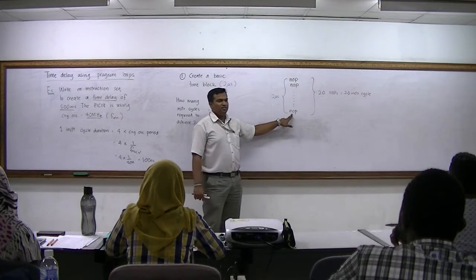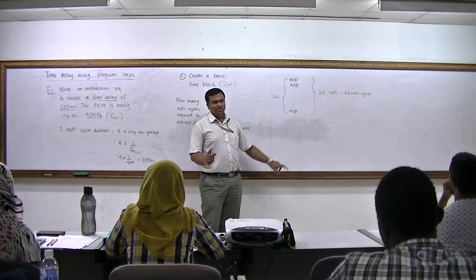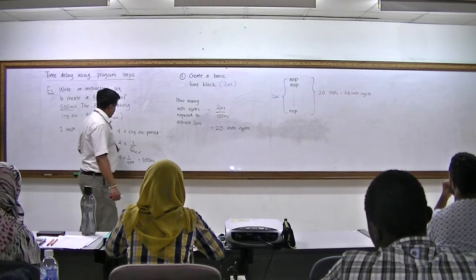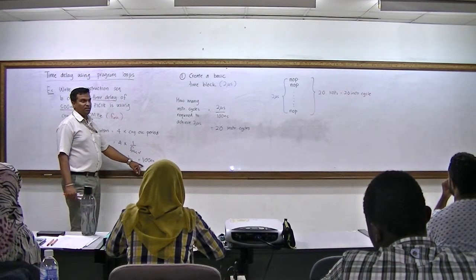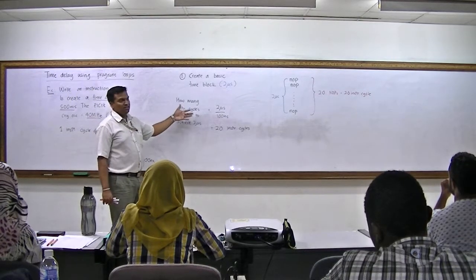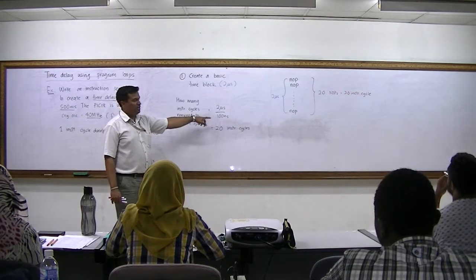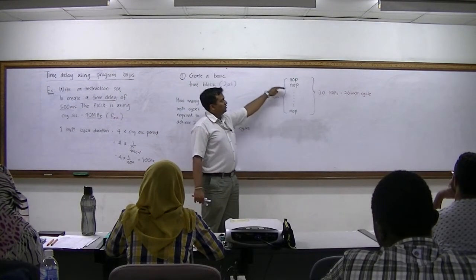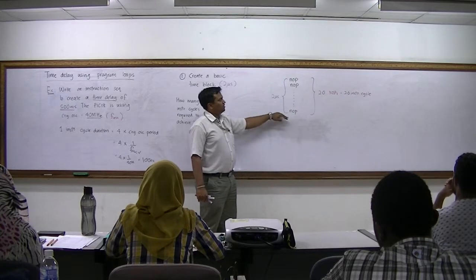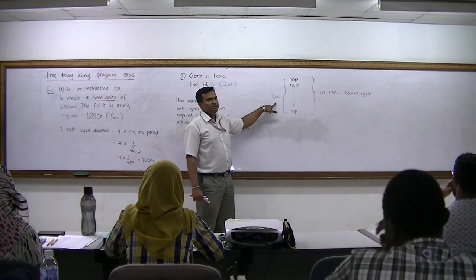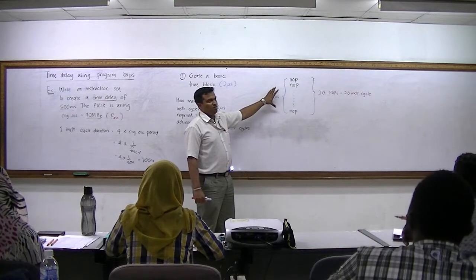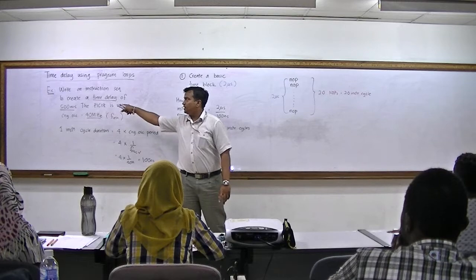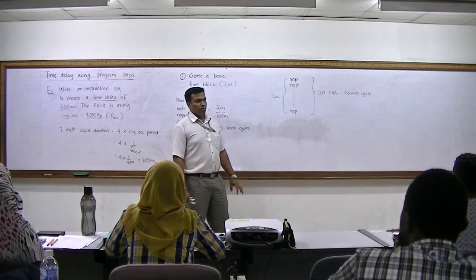Each instruction, this NOP, takes 1 instruction cycle, right? And this 1 instruction cycle actually takes 100 nanoseconds. So if you want to find out how many cycles you need to create 2 microseconds, you just divide. So you need 20 instruction cycles. If you write NOP 20 times, the time it takes to execute all this is a 2 microsecond delay. So we're going to use this as a basic time block, and we're going to multiply this to generate our required time delay. You all follow?